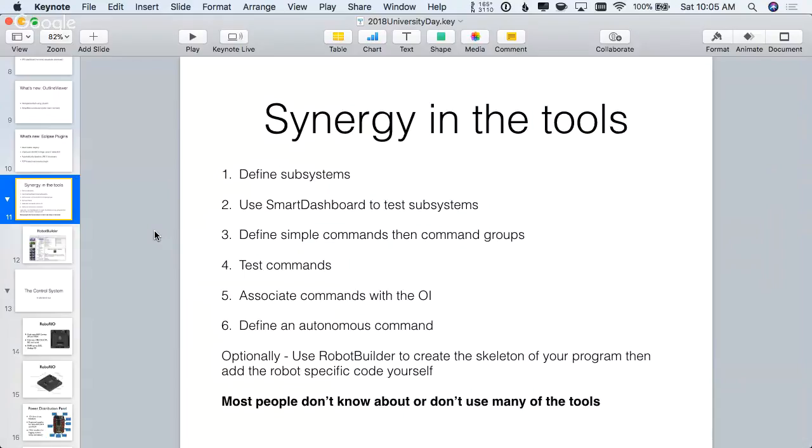You see that on the driver station. One of the little buttons on the driver station is test. So put it into test mode, and the SmartDashboard will display all of your subsystems as if by magic, and all the things which are in them. It'll have sliders for all the motors. You can test the motor and see if it's working, and you can look at pot values. So as you adjust, on this thing we have a little elevator. It goes up and down, and there's a potentiometer for that to sense the height of the elevator, and there's a potentiometer on the gripper, on the wrist, on the little gripper, so you can sense the angle of it.